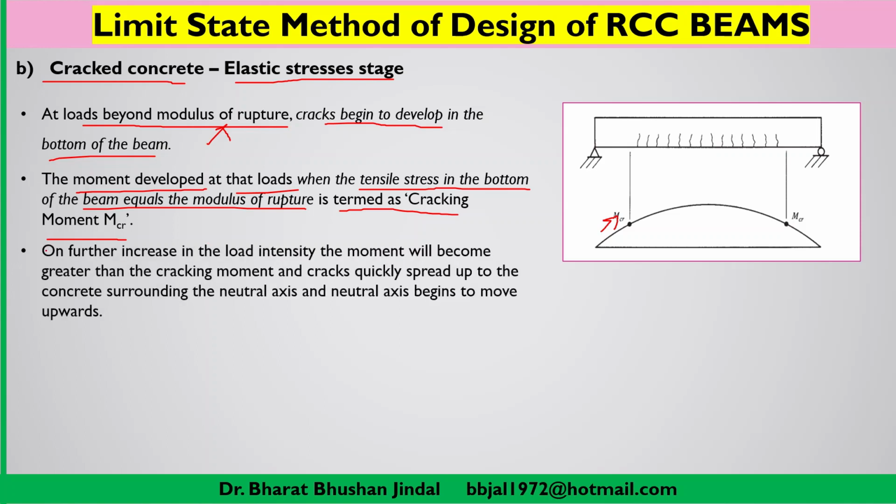Now if you still go on increasing the load, on further increasing the load intensity, the moment will become greater than the cracking moment. So here M will be more than Mcr, and then what will happen? Cracks will quickly spread up to the concrete surrounding the neutral axis. So now if there is, suppose, a neutral axis, then these cracks will start developing